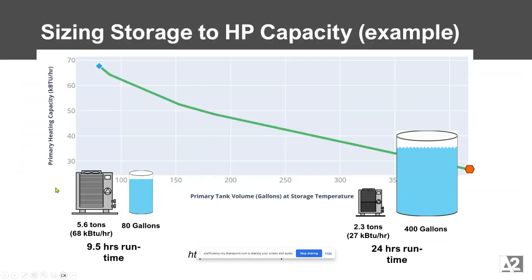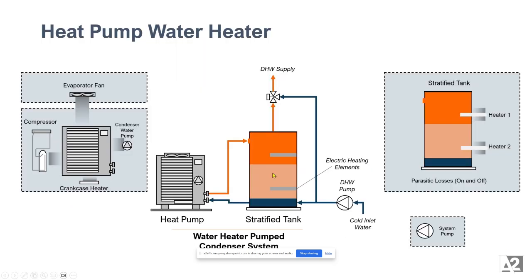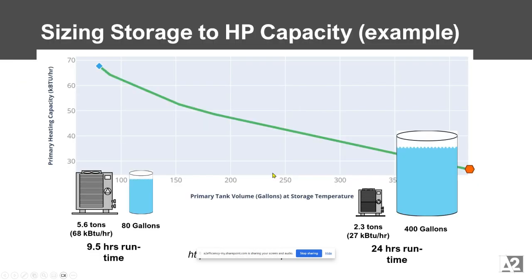Okay, well, yeah, so this is the kit of parts. This will work. So just from a concept, heat pump water heaters can be sized at two ends of the spectrum. Assume you know a lot about the system: how much water you need, the daily profile, the draw schedule, which is really the fractional schedule of how much hot water is used in a day. All that then compounded down.